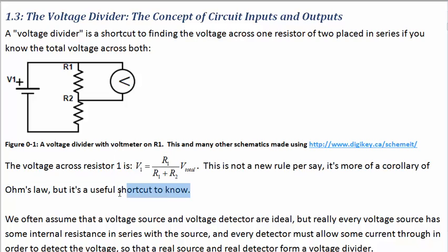In fact, you may look at sentence structures as kind of another higher level of that. So as we get to third year circuits, as we're getting better and better at this, then you want to not have to do your Kirchhoff's laws every time to figure out what the voltage that R1 gets. There's such a common circuit element that it's good to just know the voltage divider and know the result right away. It'll help in your design if you can get to this level of abstraction.